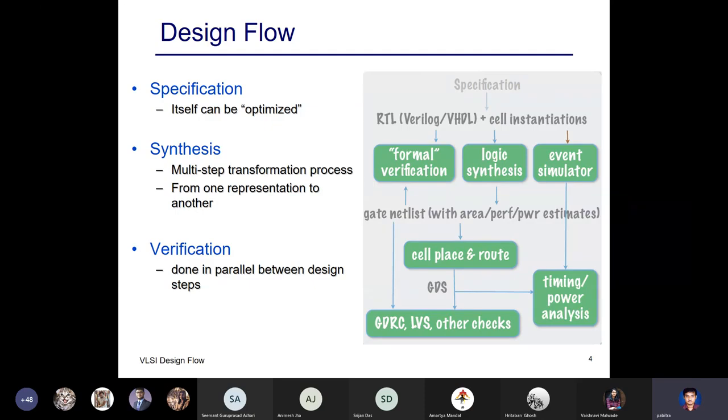For example, one simple thing: in your test benches, when you design this timing and you simulate, you intentionally insert delays. There is a command called #10. #t will mean it will insert a delay of t. But in hardware, it depends. If you are using CMOS, it will actually have a delay.